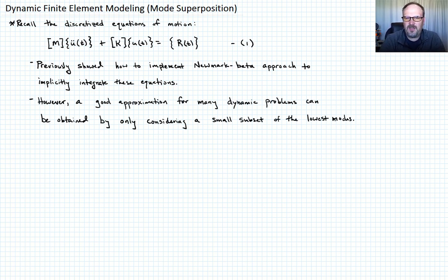In addition to the wind turbine example, another example might be modeling an earthquake. You want to see how an earthquake is going to affect a building. The nature of the frequency that the earthquake is vibrating at, versus all the possible frequencies in that building, means that maybe there are 1,000 or more modes in your building, but you probably only care about maybe the first 20 modes. So what kind of a method could we develop to exploit that we only care about a subset of the entire dynamic response?